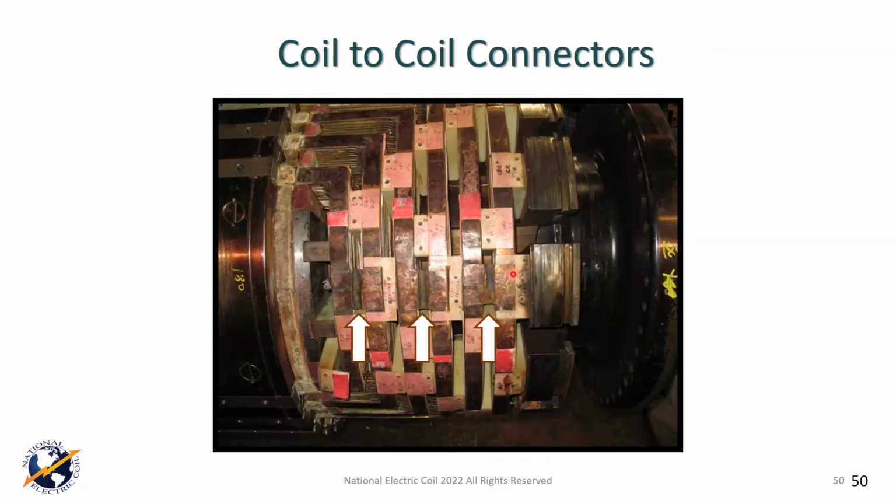And on the bottom is where we would have that pole-to-pole connector that goes from the one pole coil 6 to the other coil pole 6, and has flexibility in between it, so that as this unit's coming up to speed and wants to expand, when it's coming down, that flexibility keeps the material from forming cracks that propagate from that stress of flexing back and forth like you would a coat hanger.